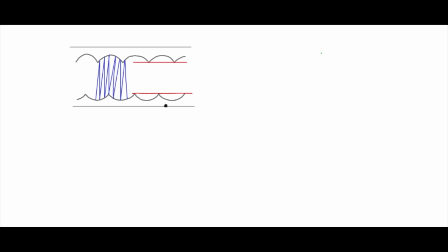This portion, if you see, and if I call that envelope x and the bottom envelope y, and if you take x minus y, you will get something like that. This is a third harmonic signal. So this third harmonic signal can be added to the carrier.